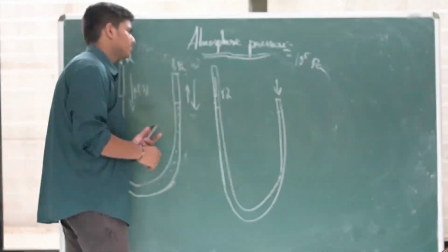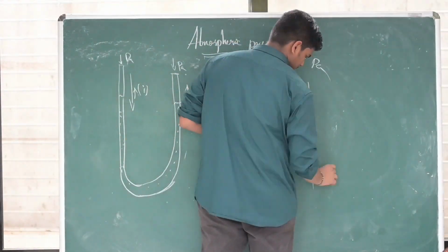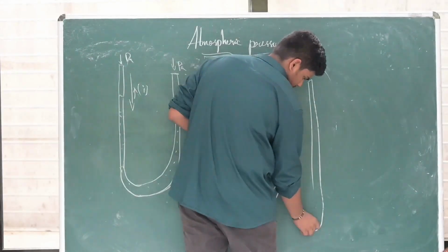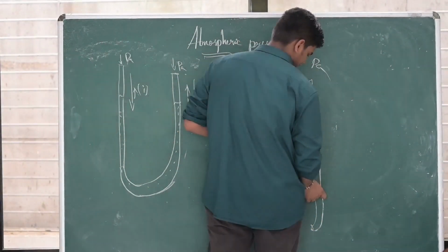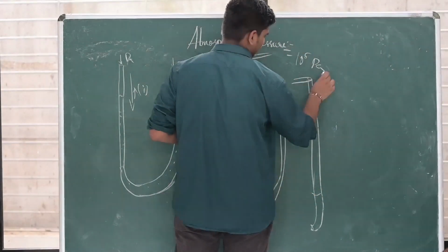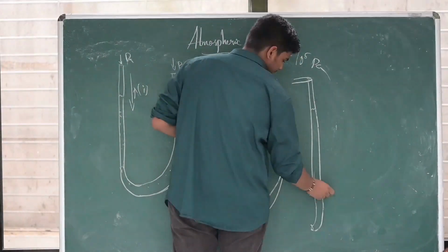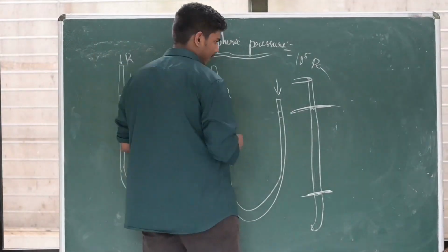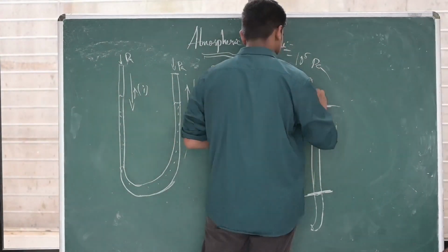Okay. Now, in case 2, why is the liquid not falling? Imagine there was this setup. I covered this part of the tube with my thumb. What happened? The fluid stayed till here only. It did not flow out. Why? There is trapped air which has pressure.